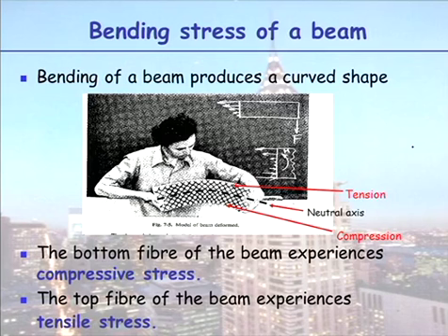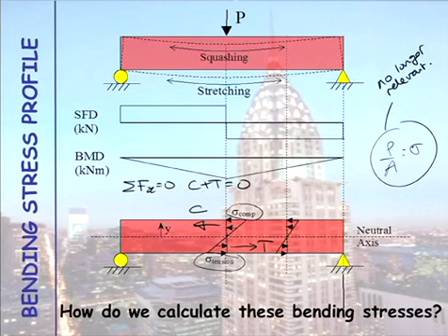We get that curved shape, and thus our stress distribution is no longer uniform, but linear. We assume it to be linear, it's linear elastic. So in this case here with a downward load you would get tension stresses in the bottom and compression stresses in the top. What I then ran through at the end of last lecture was the proof of the formula.